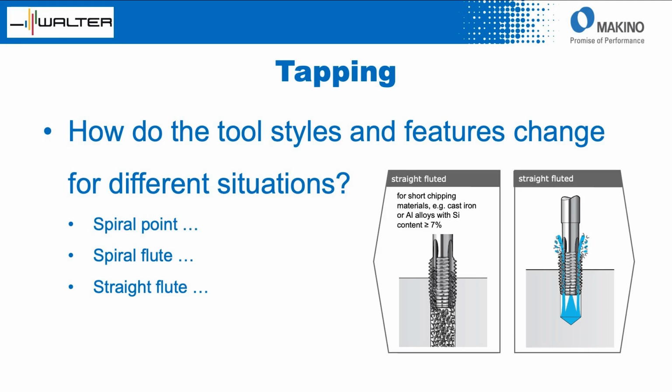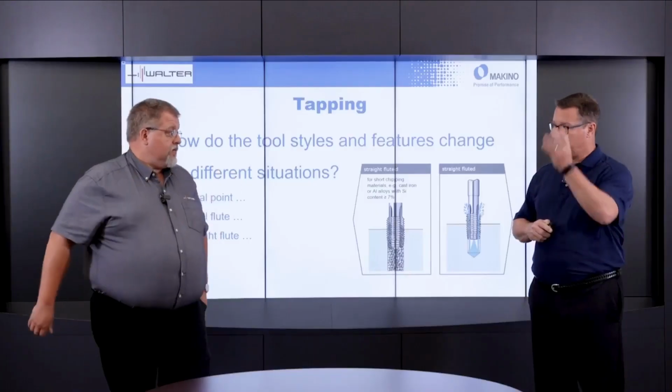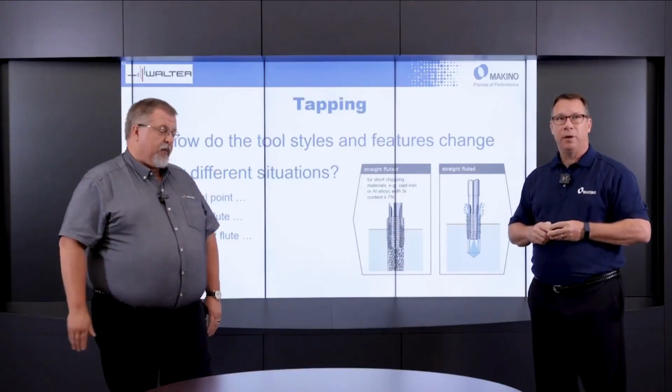But what we do look at here is in the blind hole situation, you're going to have to use some coolant to get those chips up and out of that hole. Okay, so basically flush those guys right back out. Yeah, we don't want to run into them.